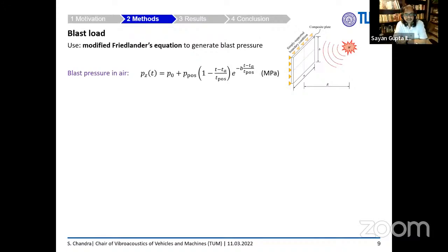The other question that I had was, is there any reason why you did not consider random field models? Because with random variable models you are basically assuming that the correlation length scales are much greater than the spatial dimension of your structure. That's when you typically consider random variable models. And here you are considering only a 6x6 plate. But when you are considering very large structures like the fuselage of an aircraft, or even wind turbine wings, the length scales are very large. So does it not mean that you should consider random field models rather than random variable models?